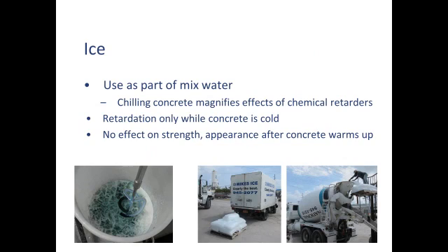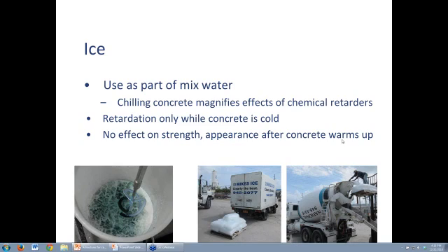The whole point of using ice is your hot ingredients melt it, and if you don't add too much ice, which you should never add too much ice, by the time you're done mixing, all the ice melts. And guess what? Ice floats, so you can always see unmelted ice because it's right at the surface. It's very easy to see. And in the bottom photos on the left is a GFRC mix we're making with ice. It's very, very common and is always done in commercial GFRC to use ice because your concrete is very predictable when it's the same temperature.